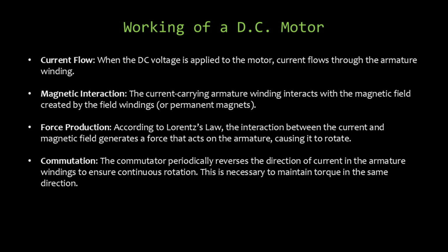According to Lorentz's law, this interaction generates a force that acts on the armature, causing it to rotate. The commutator plays a crucial role by periodically reversing the current direction in the armature windings, ensuring continuous and smooth rotation.